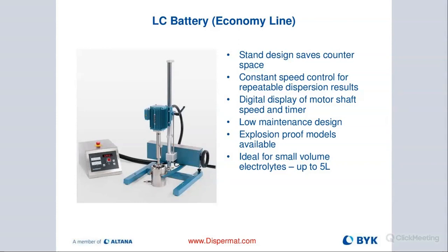And then the disadvantage I want to point out on this particular model, this is my opinion, is that you have to manually raise or lower the shaft. You can see on the left, right side, that lever. You loosen that, and that allows you then to move the motor head with the shaft up and down along the stand. Personally, I don't like it that much because it's difficult to oscillate or find the sweet spot of the blade inside of the container.